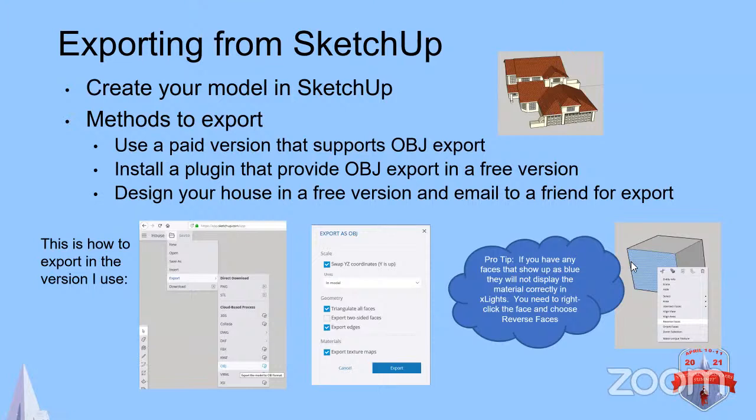And then one tip I threw in here, if you do work in SketchUp, whenever you see a surface that looks blue instead of white, you're really looking at the back side of the surface, because any surface can be flipped. What'll happen is if you have a blue surface like that and then you add a material to it, when you import it in xLights, and because you weren't doing the two-sided faces, that's an inside face, but it's being shown on the outside because it's flipped. You really need to go back in SketchUp, select that face and do a reverse faces. It'll turn white, and then your material will show up when you bring it into xLights.